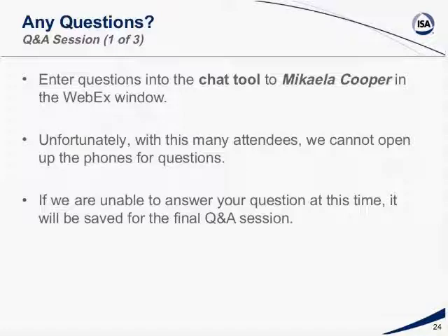I'm a strong proponent of having a philosophy before the DCS selection because you don't want to have a DCS that does not support some of the things you want to do. For example, if you really want to get into heavy state-based alarming, things like that, you want to have a DCS that will support that. And so having a philosophy document in place prior to selecting a DCS is a very, very good idea.